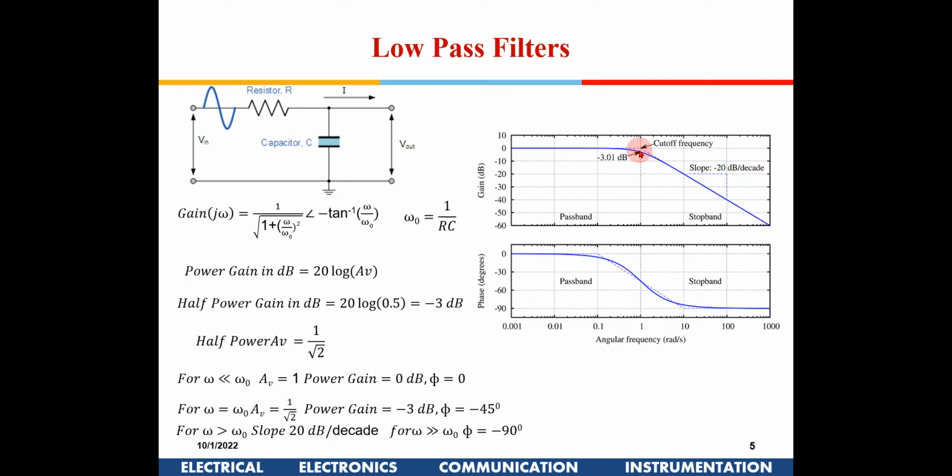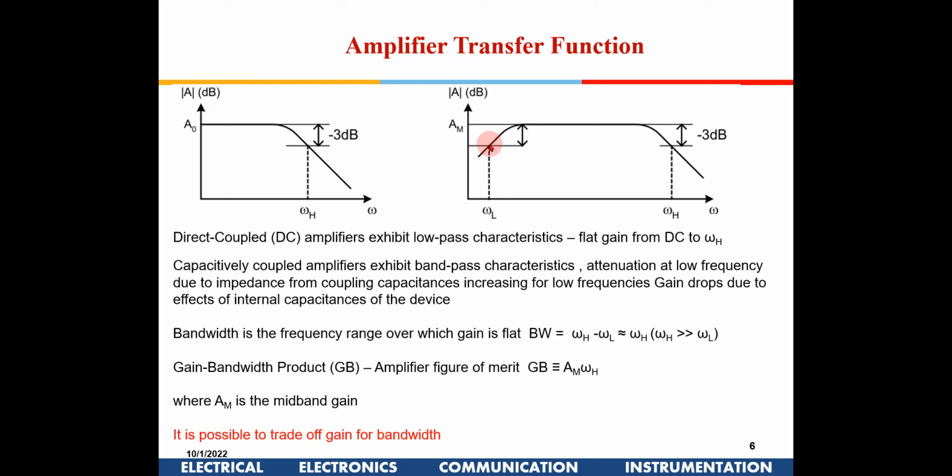So generally an amplifier will be a band pass, whereas very low frequencies might be attenuated like this. So you can have any frequencies below WL, the corner frequency. When I say bandwidth of a circuit, it means that at WL, the lower limit, it will be 3 dB down from here to here. Similarly, this is also 3 dB down at WH.